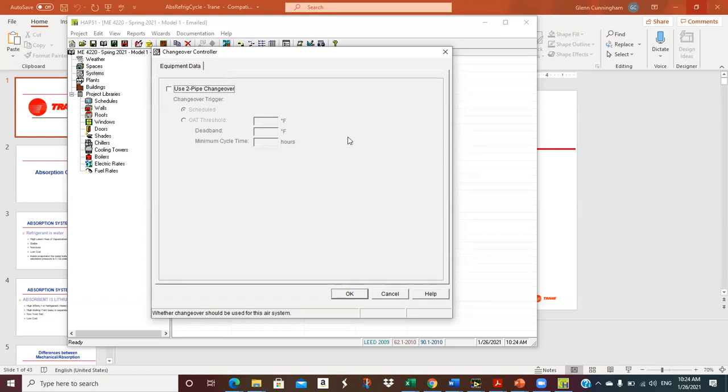So then the automatic control system has to turn off the boiler, continue to circulate the loop until it gets down to whatever the desired set point is, 75 or 80 degrees. And then you fire up the chiller and you keep the valve shut on the unit. And then the chiller just cools down the loop until it gets down to 42 or 44. And then the units can start cooling. And this process may take 3 or 4 hours.